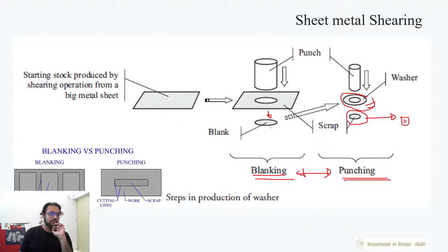So in this one also it's the same thing. Let's say this is a piece of sheet metal and you are cutting, so that you want to use these gray areas which do not have lines. So this is a blanking operation. Now there's another operation where this is a piece of sheet metal and you want to remove this hole, right? And this will be thrown away and this will be used, right? So this is a punching operation. Okay, so these two are like simple differences.